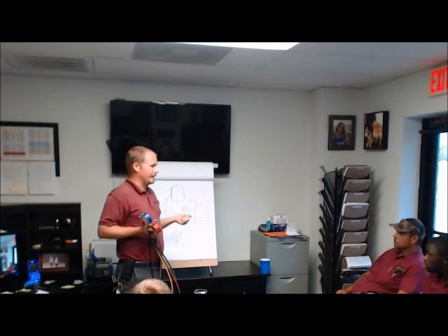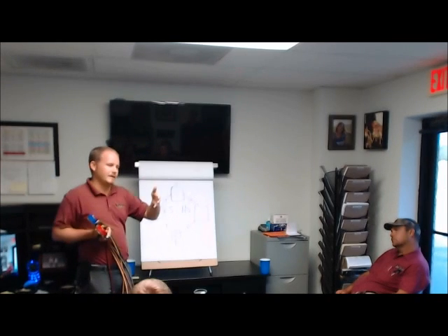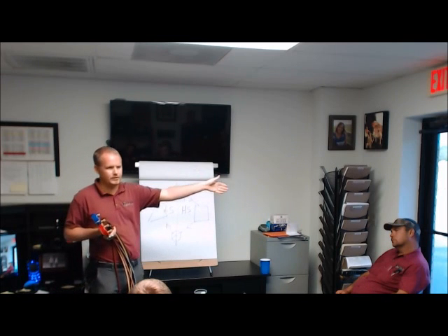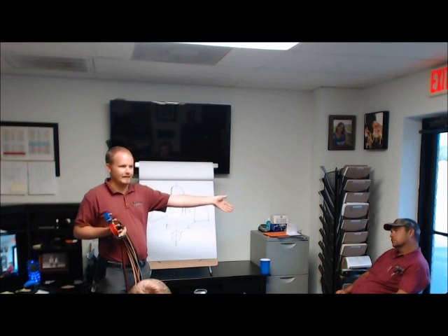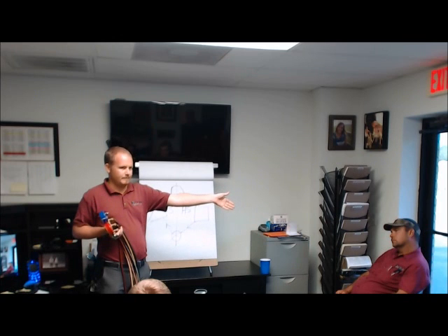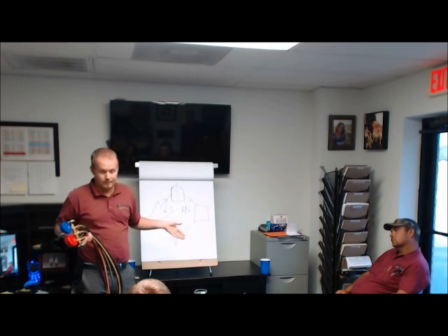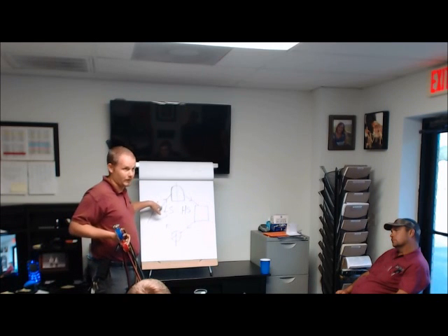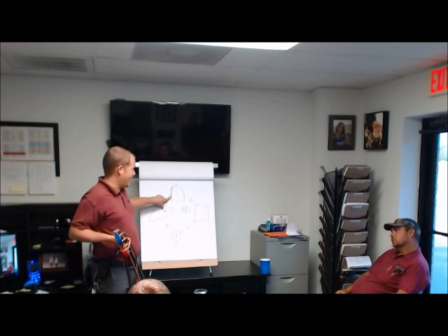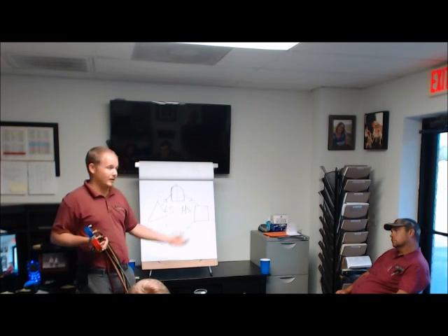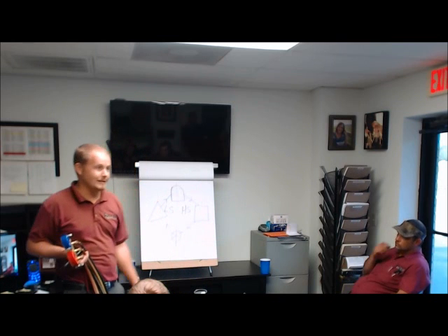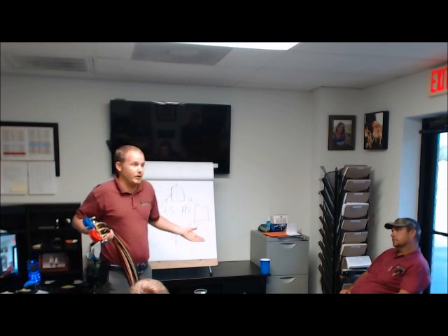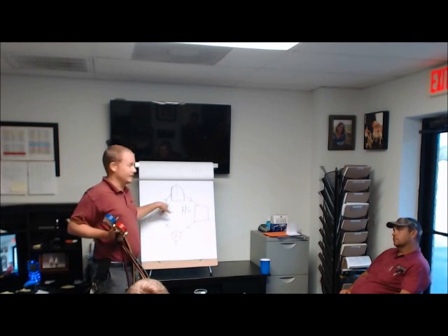People will say something like, and I'm jumping ahead of myself, but for the technicians here, someone will say, "Hey, this TXV is supposed to maintain a 6-degree superheat." Well, where's that TXV maintaining the superheat? At the evaporator, because where's the bulb mounted? On the evaporator, on the suction line. So it's measuring it here, and so we're taking a superheat where? Outside. Out here. Well, does that TXV have any idea whether or not that suction line's insulated, how long the line set is, any of that stuff? Whether it's got a 40-foot rise in a condo? No, it's got no clue. It's trying to do its job at the outlet of the evaporator. It doesn't know what's going on here.